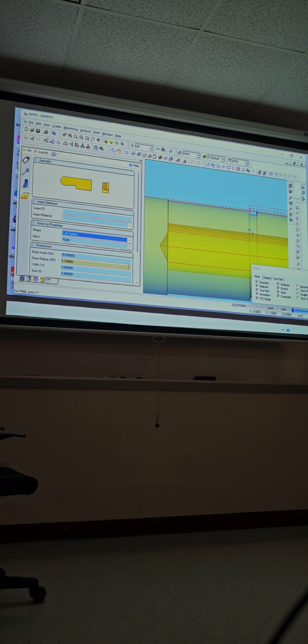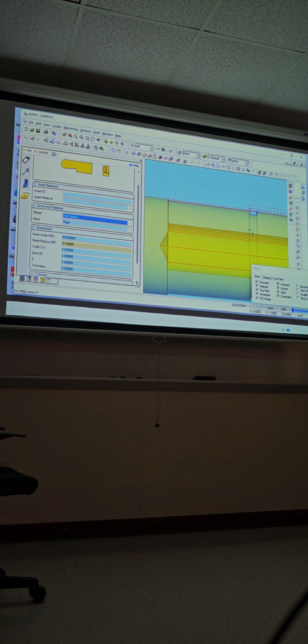And now we'll see over here what we need. All right, so nose radius .125. So the width is .250. At least, and we're going .150, .125. Radius is .125. So let's be safe and let's put it .100, so it can go in there. Size on the back, .300. Let's put it at .300, so you've got plenty in the back. So let's double check this, full radius. The width is .100, and we're gonna go .125. .300 in the back.